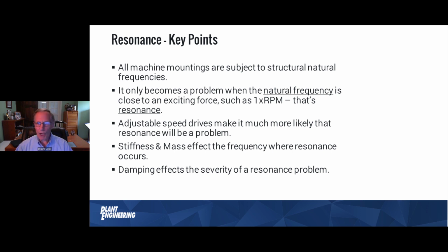It's always been a problem with machines for as long as we've been doing vibration analysis. The more recent development of variable frequency drives or variable speed drives has made natural frequencies and resonance more of a problem, because machine speed now is pretty likely to find one of those natural frequencies as you move it back and forth.